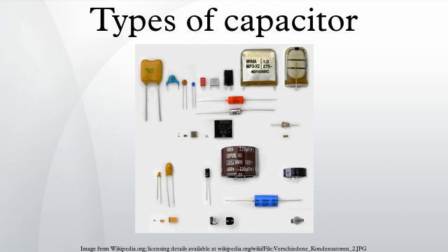Theoretically, given two capacitors with the same mechanical dimensions and dielectric, but one of them has half the thickness of the dielectric, with the same dimensions this one could place twice the parallel plate area inside. This capacitor has theoretically 4 times the capacitance of the first capacitor but half of the voltage proof. Since the energy density stored in a capacitor is given by